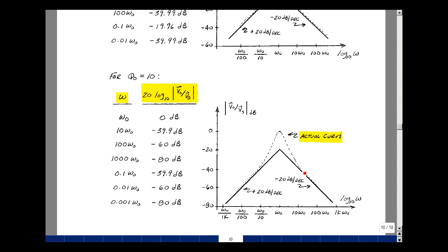On the other extreme here, if we go higher and higher in frequency with respect to omega naught, we decrease in value, so get more and more negative dB, and we're approaching again a gain of 0. And then when omega equals omega naught, we see a gain equal to 1. Does the circuit do the same thing?